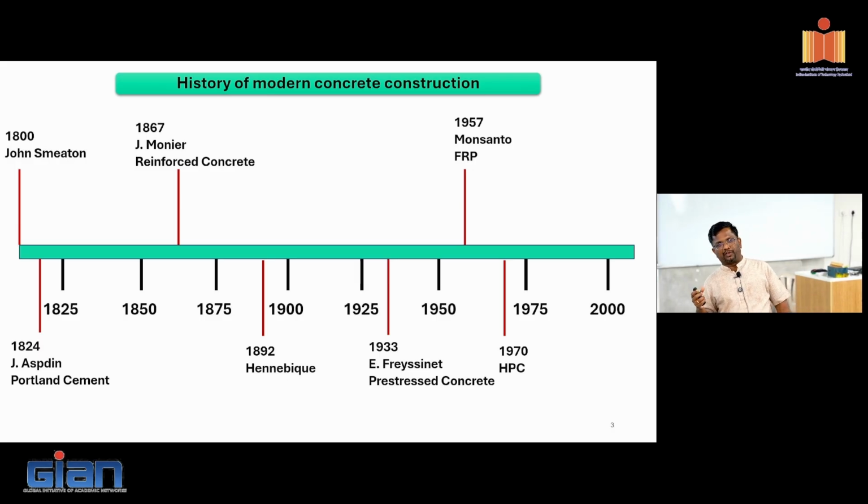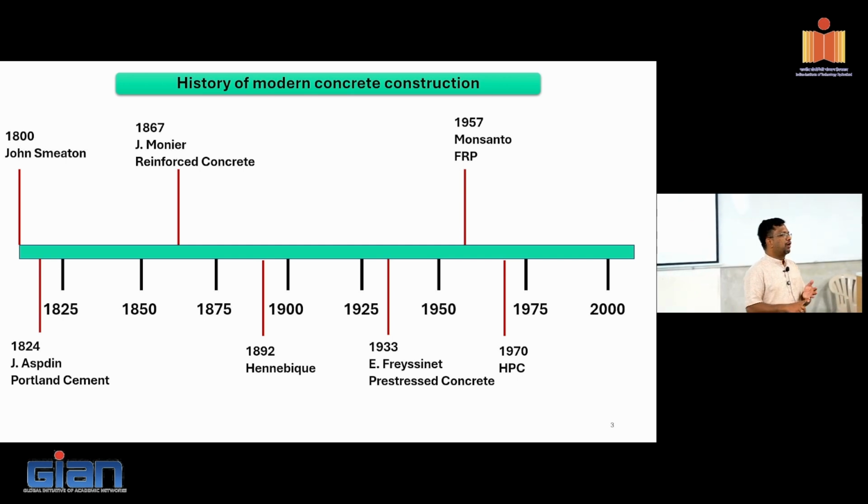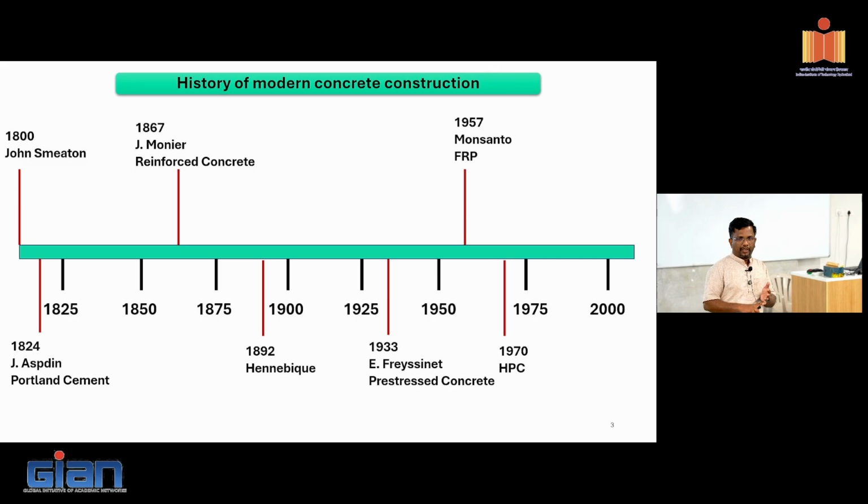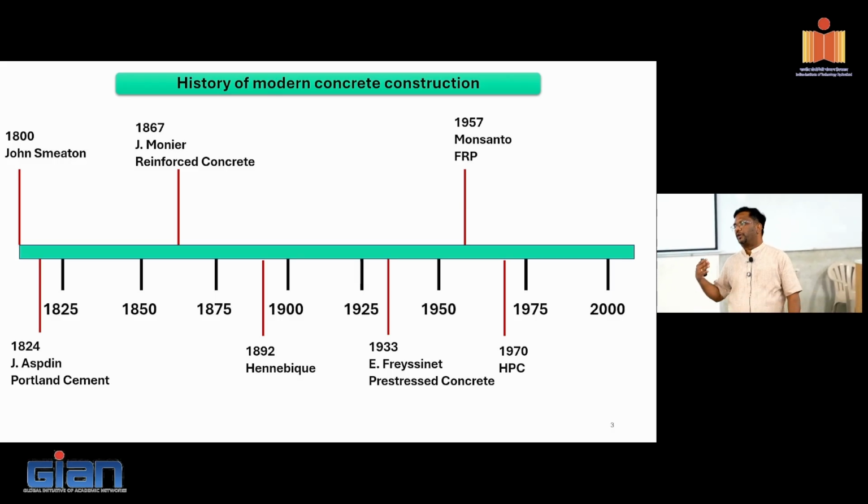So with high performance concrete, you don't talk only in terms of strength, but more in terms of durability, right? You make the microstructure so dense that deleterious substances like chlorides, sulfates or water cannot get into the system and start electrochemical corrosion in the reinforcing system.